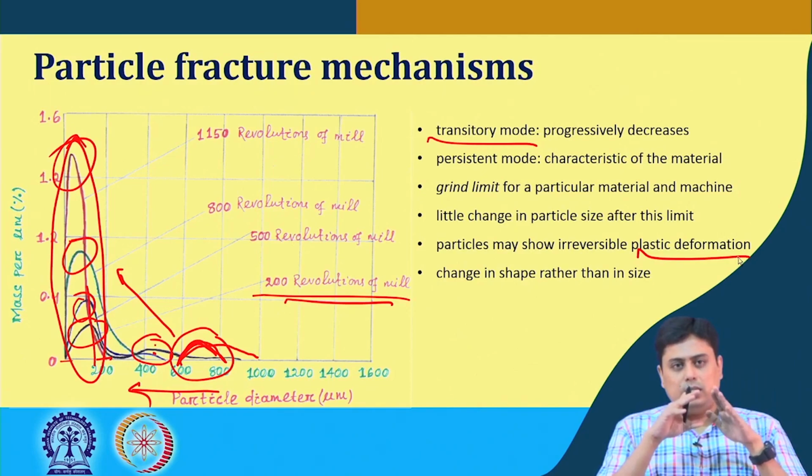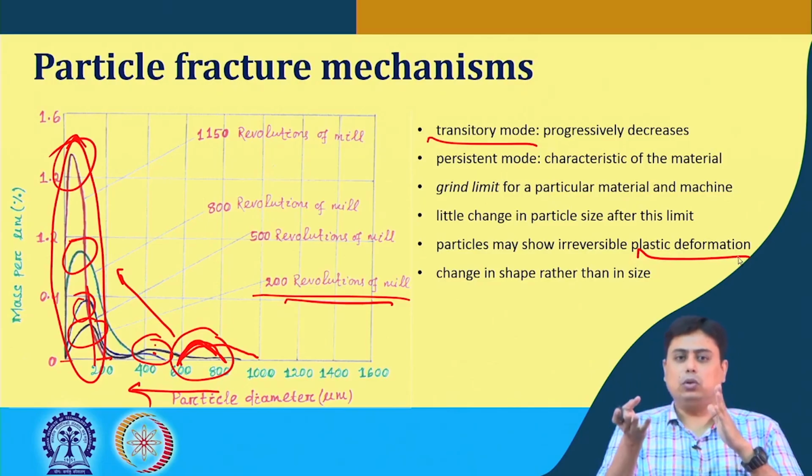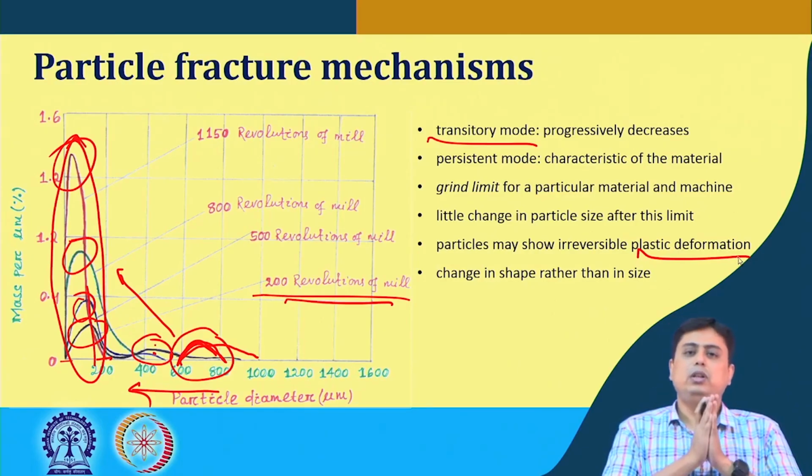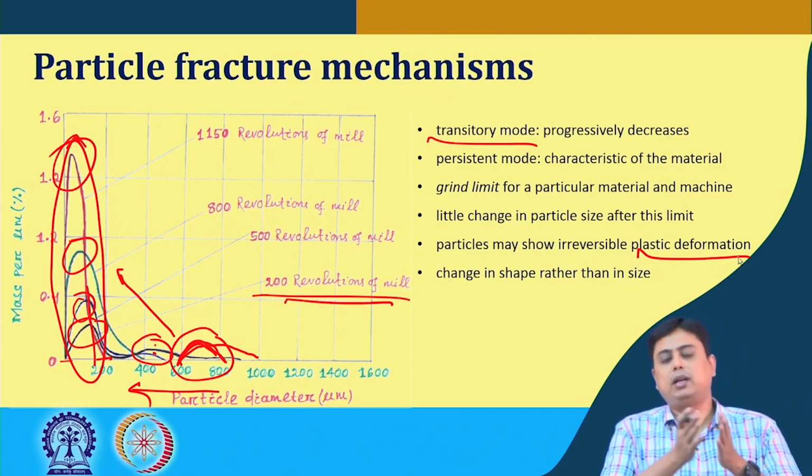And there is the grind limit, applicable for both, it is the limitation of the equipment as well as the characteristic of the material. So, beyond that limit, the particle size will not be further reduced by that particular equipment.